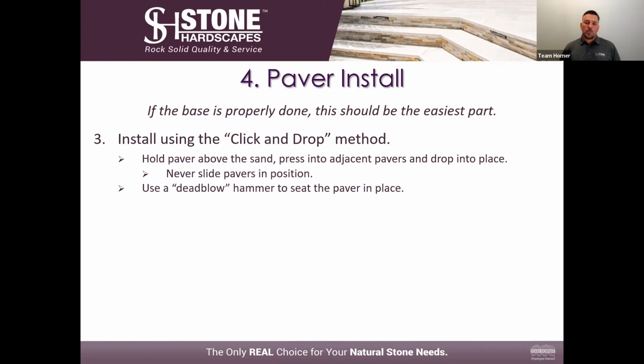So you want to install the paver in that click and drop method. Hold it above the sand, put it against the ones next to it, drop it into place. Then you want to use a dead blow hammer. And it's very important to use a dead blow hammer. And you tap the paver as you're putting it down to seed it into the sand.